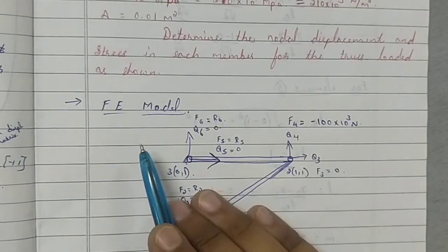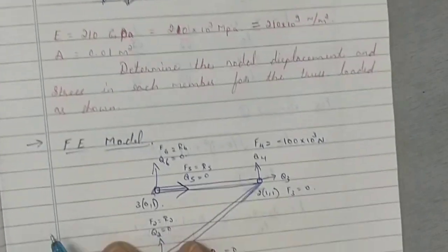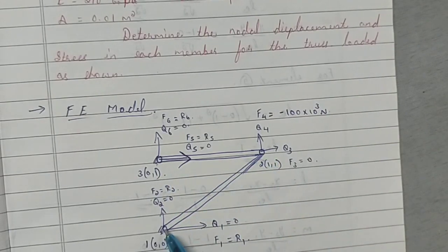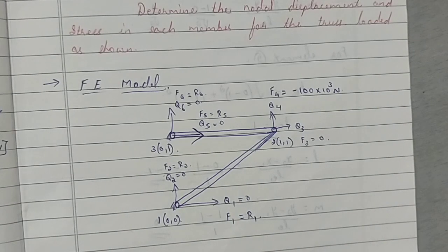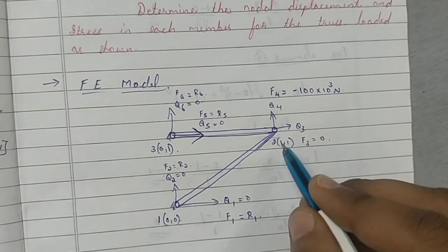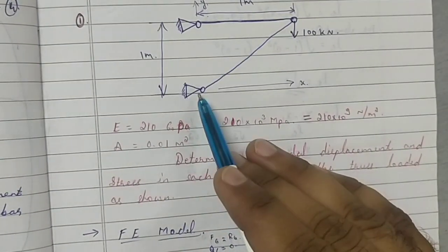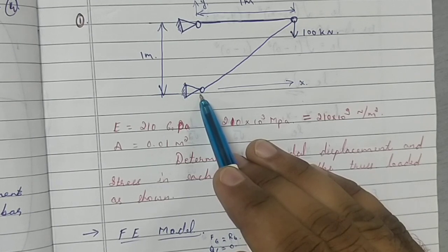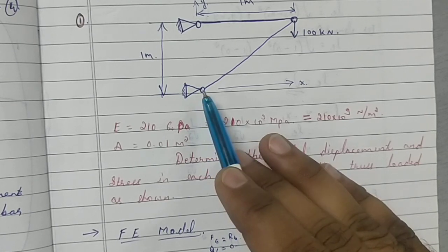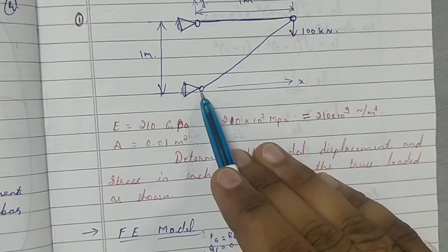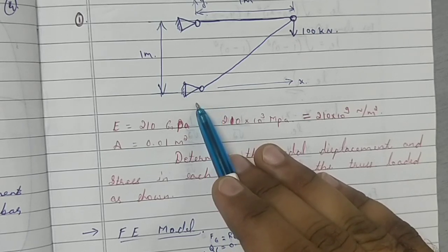Okay, so write the finite element model from this. Write the similar line diagram with this and this fixed. Start numbering first. This is a very important step. If you understand this step, rest everything is very easy. Start naming. So this is node 1, node 2 and node 3. Write the coordinates of each node. Always the origin must be left bottom corner in the truss. I repeat, the origin should always be left bottom corner unless and until they have specified the origin.